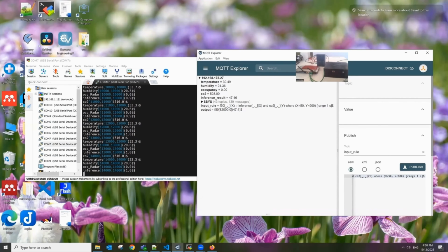Let us start the application and see the printed output of the serial port. On the left, we see raw sensor data along with occupancy inferences from the tiny ML model. On the right, a simple MQTT client is used to send micro CEP rules to the Target 5 device. Once the 3 rules are uploaded, new events appear immediately.